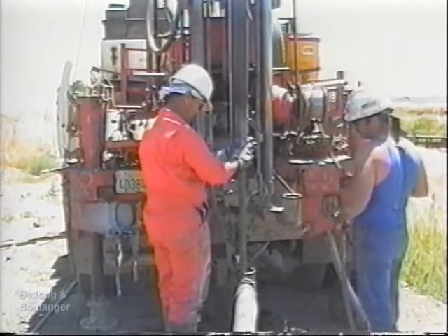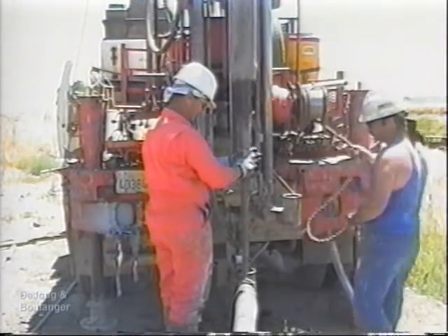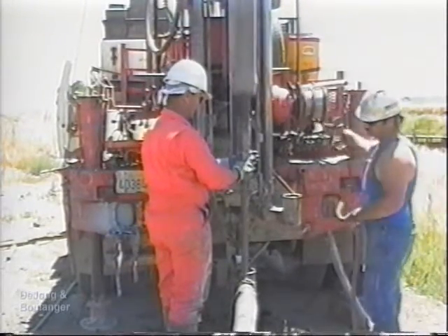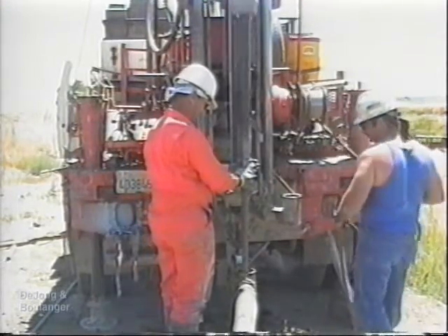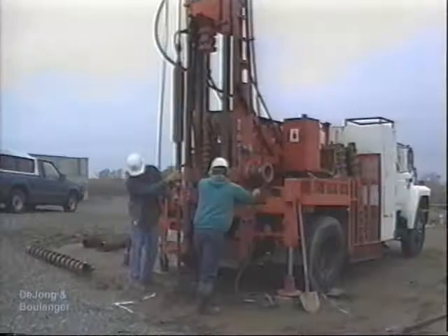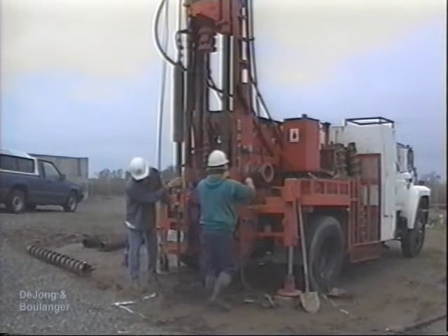Mechanical trip hammers provide a more repeatable energy input, while the energy from drop hammers can vary as the driller becomes physically tired and slowly reduces the hammer drop height, number of blows per minute, and other variables. Thus, it is highly recommended that the energy delivered by a particular drill rig be calibrated on important projects.